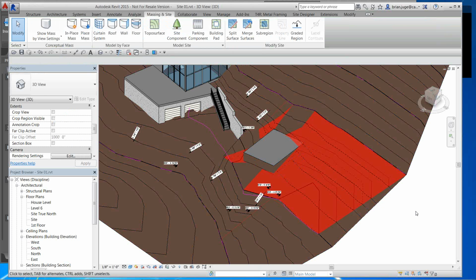All right, so Brian, how would you make a point and origin point in AutoCAD? And also, if you reset the coordinates, does that not negate using real-world coordinates? Yes. If you reset the coordinates, I'll answer the second question first, you are negating the real-world coordinates. Here's a reality check. We don't use real-world coordinates in Revit. What? Yes. Surprise!